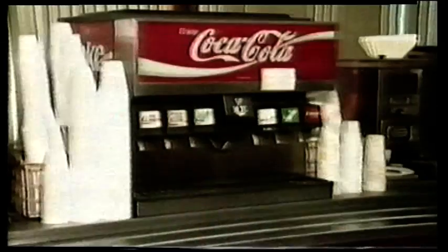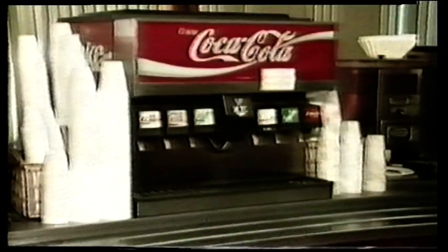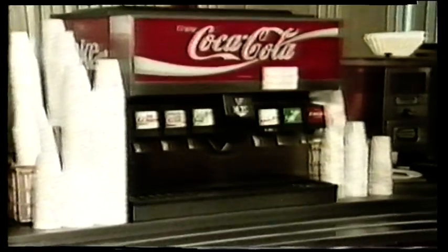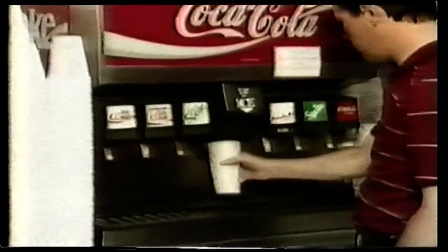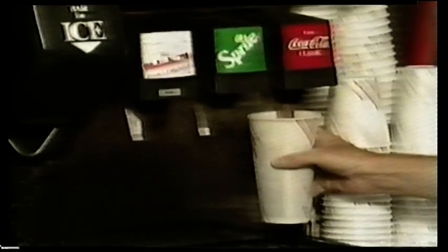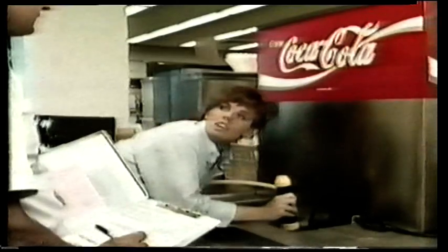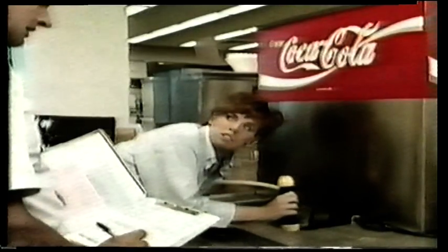If the machine is bottom-loaded or no schematics are available and inspection is not possible, a backflow prevention device or assembly should be installed as required by regulations. Some beverage machines are post-mixed, utilizing a water supply connection to produce a carbonated beverage. Post-mixed beverage machines, both coin-operated and self-service, can be extremely hazardous in the event of back pressure and a failed check valve condition. Carbon dioxide in the soda water can react with the copper tubing to produce toxic copper carbonate.